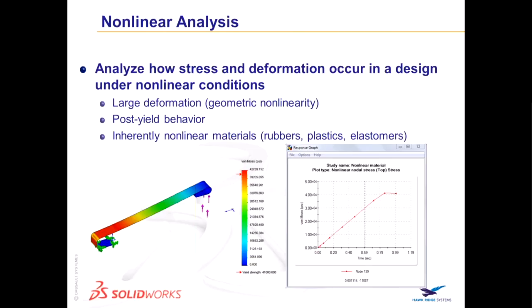And that essentially is any situation where the part that you've designed or the assembly that you've designed is being deformed beyond that small displacements range, that small displacements assumption. And it's not necessarily a fixed number or anything like that, but a good guideline is if you can imagine your product being deformed in the real world with whatever loads you've decided to put on it, if you are likely to be able to see clearly that part deforming, it's probably beyond the small displacement range.